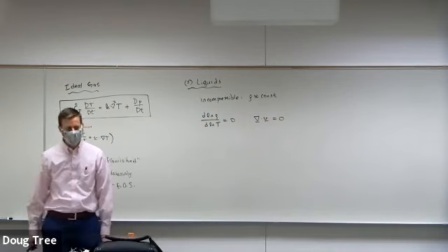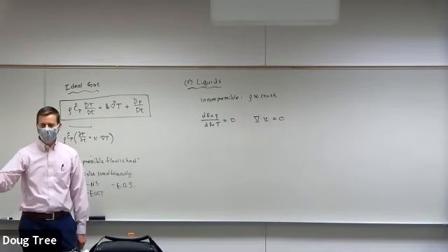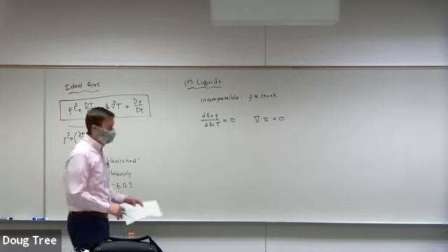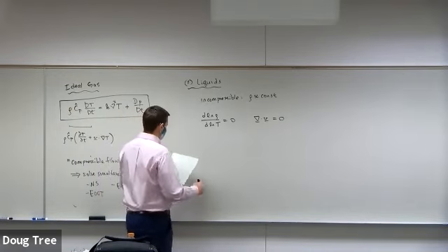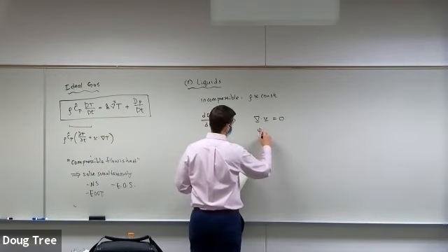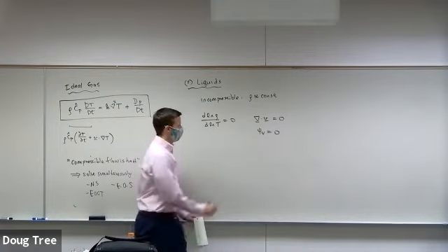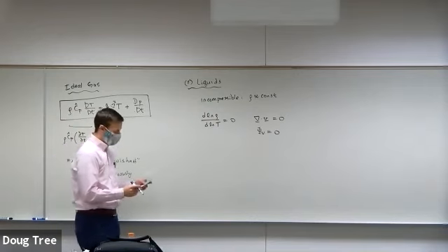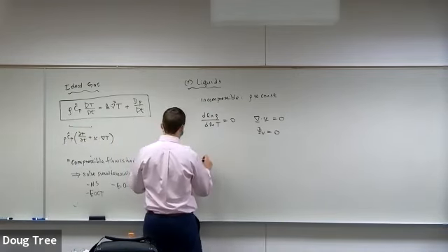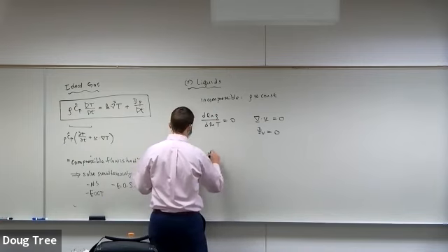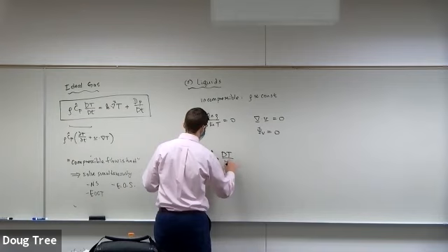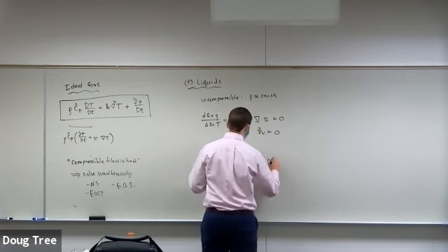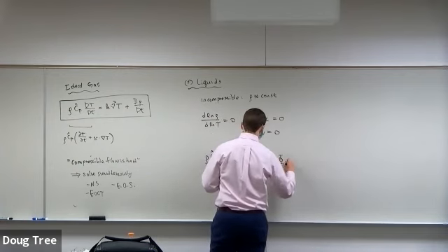That's the continuity equation. So I can't have this expansion or contraction, right? Because the density has to be this constant. So I can't do that. That means that this term psi V is equal to 0. Because remember, psi was the del dot V squared. Okay, so that guy's 0. So this makes my equation of change look like the following: DT Dt is equal to k grad squared T plus mu phi V.